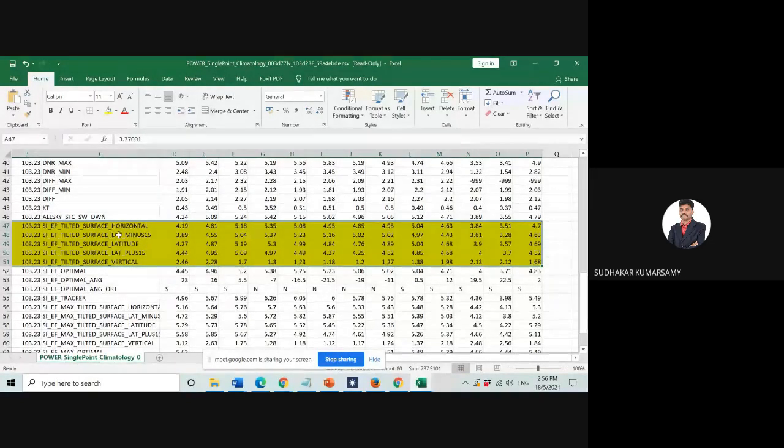So you got an idea now that if the solar panel is placed exactly closer to the latitude, we get a better collection. And the next one, maybe you can keep on doing this exercise: latitude slightly higher, slightly lower also, like plus 10 degree, then again minus 10 degree. You can do this analysis by doing an interpolation, extrapolation and all, and then you can get the closer value also. Because if you know these two values, you can try to find the latitude minus 10 degree and latitude plus 10 degree also. So this exercise you can do and plot it for a given location.